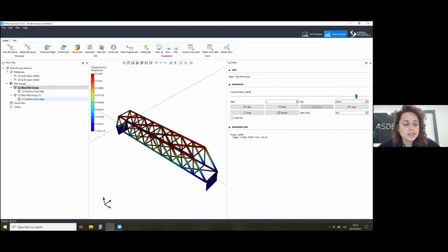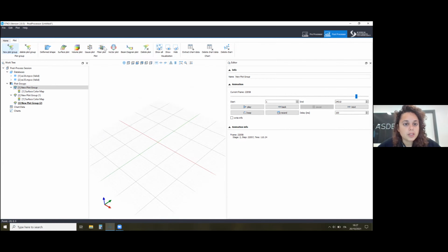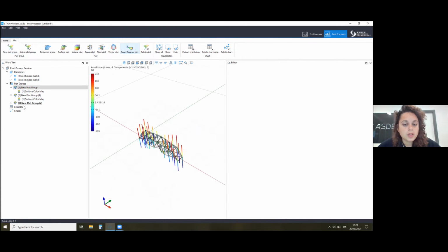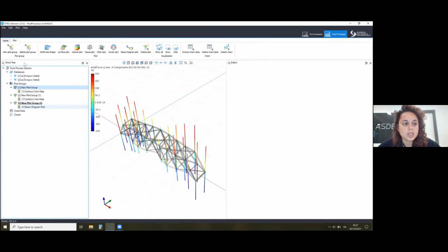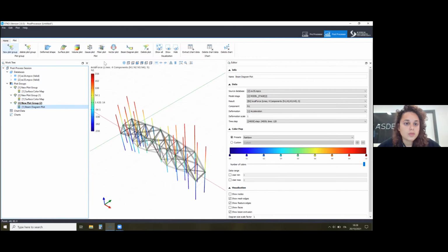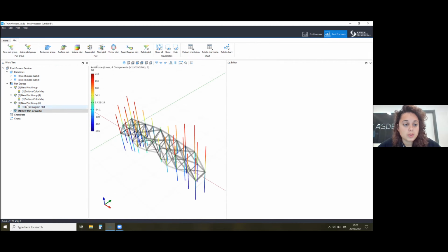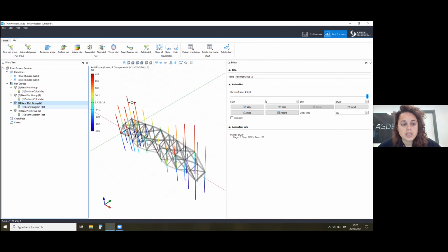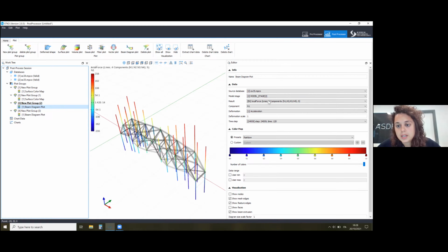So how can I check that I did something different in these two models? Something that you can ask for in the recorder to check this is the local forces, because we're using beams, so local forces can give us information at the extremity of the elements, and we can see what is actually happening there.